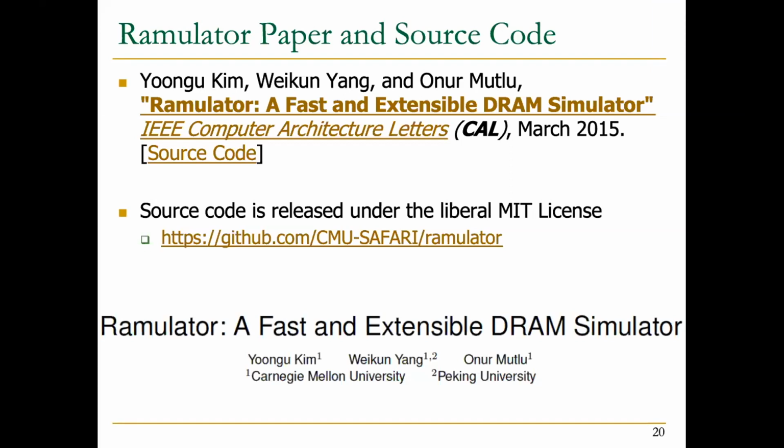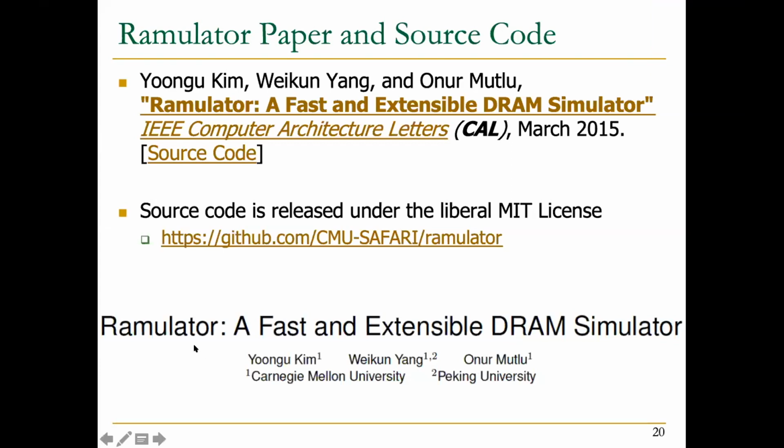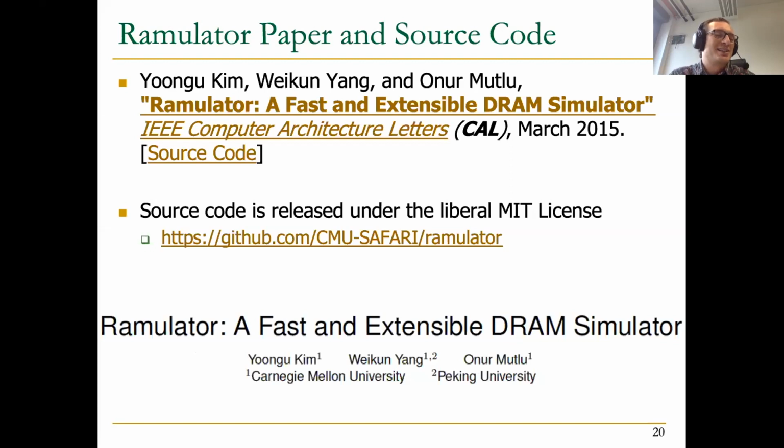So you somehow saved the trace of the commands or something like that, and then compared it to this golden model. Exactly. You create a trace of commands, and you run it through the golden model, and then you run it through Ramulator, and you look at the actions that each of them takes. If they are consistent with each other, assuming the golden model is correct, of course, then Ramulator is also obeying what the golden model is doing. All right, I see. And that's a good way of verifying the simulator, assuming a golden model exists.